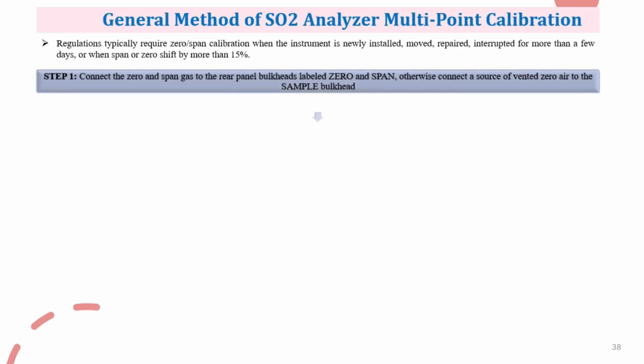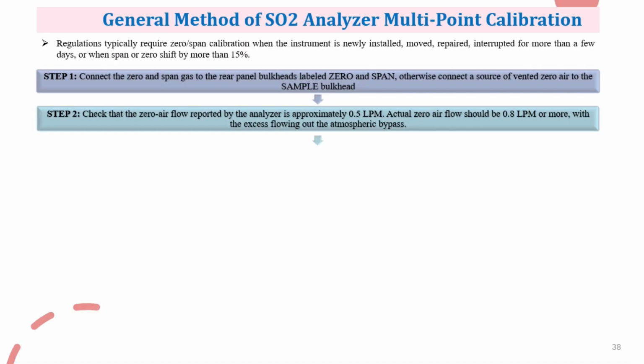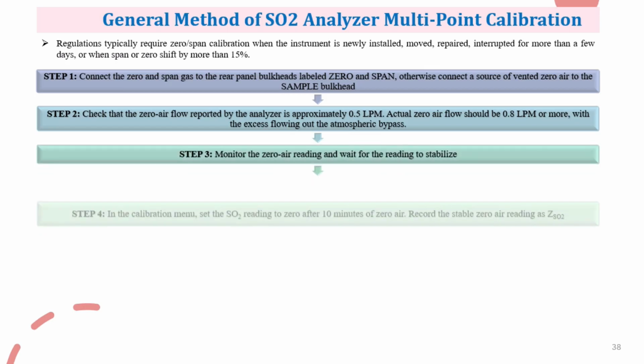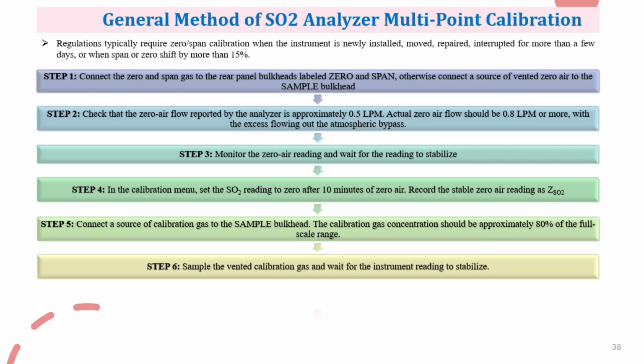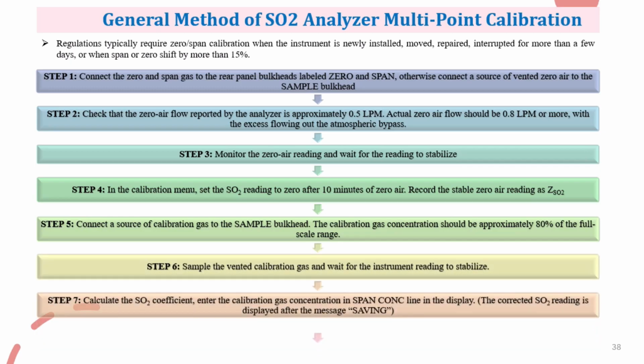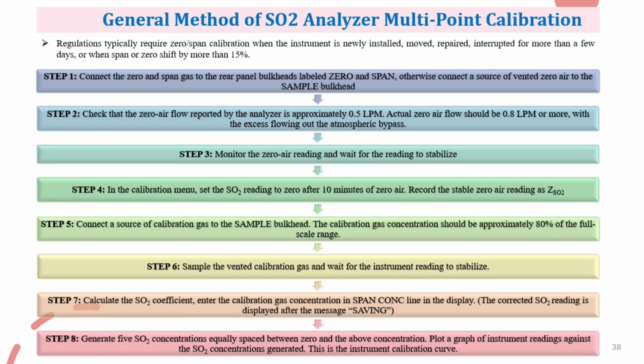This diagram shows how the analyzer works step by step. It starts with the excitation of SO2 molecules by UV light, which then emit a special type of radiation. We have components like a UV light source, a beam splitter, a photodiode, a photomultiplier, a phototube, and an electronic signal processor. These parts help us to capture and process the light and data as they flow through the system.